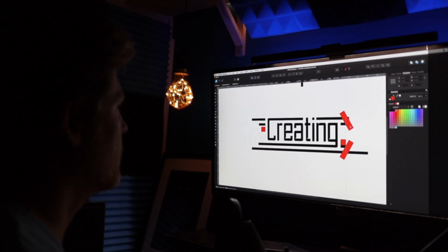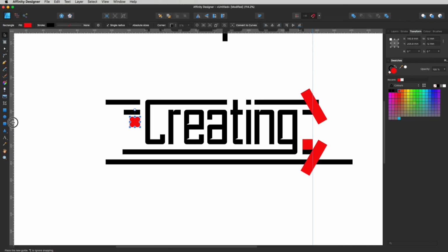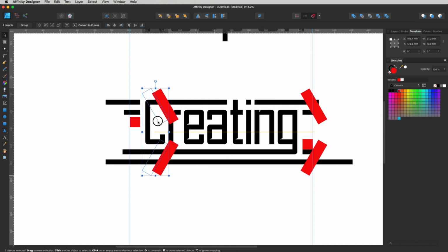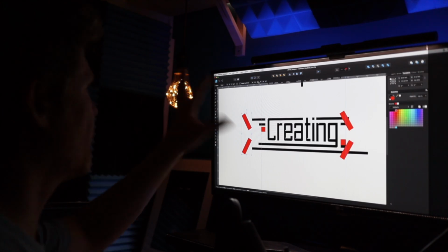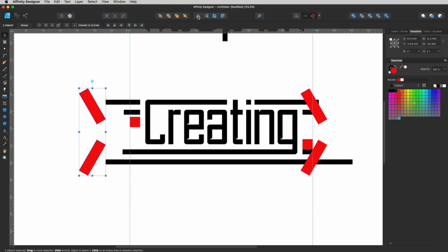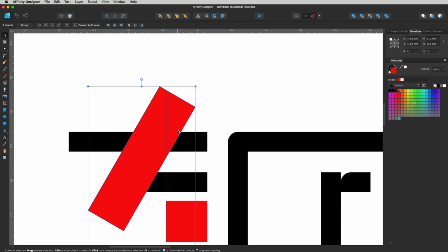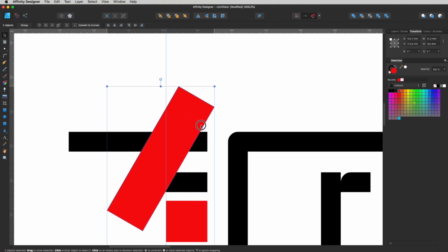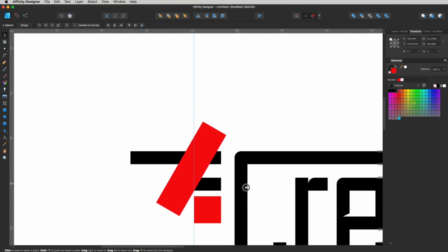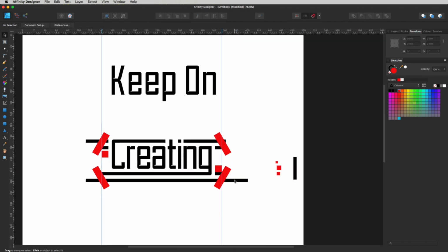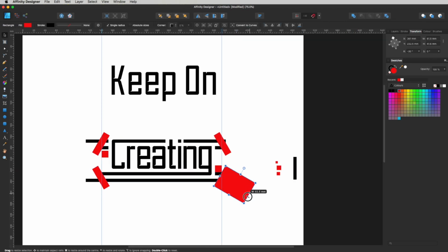And I'm going to take this section over here to get my ruler on that side. It's on the outside. Click those, Alt drag them right across to this side. Let's just flip them right over. Just click on this little button over here. It flips them. And I'm going to hold shift, drag them in right to where they intersect again, right there. Okay, cool.